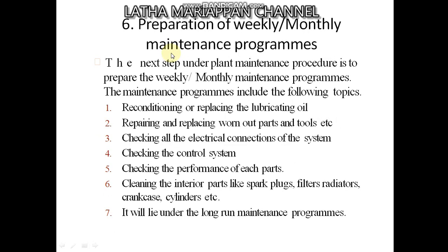The next step is preparation of weekly or monthly maintenance program. So here the maintenance program includes these topics: reconditioning or replacing the lubricant oil, repairing and replacing worn out parts and tools, checking all the electrical connections of the system, checking the control system and the performance of each part, cleaning the interior parts, and it will lie under the long run maintenance programs.